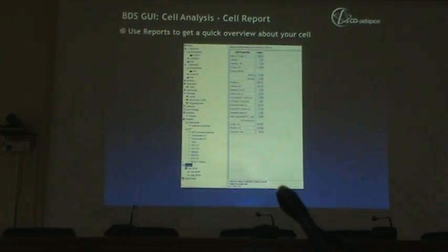Once you create the cell, you give a load file. By load file, what I mean is, let's say you want that particular cell to run at a 1C rate for this time at this particular temperature. So you have to provide those load files, and once you provide them and you run them, you have the results available generally in a graphical format. So you can always discretize them and use the data later.